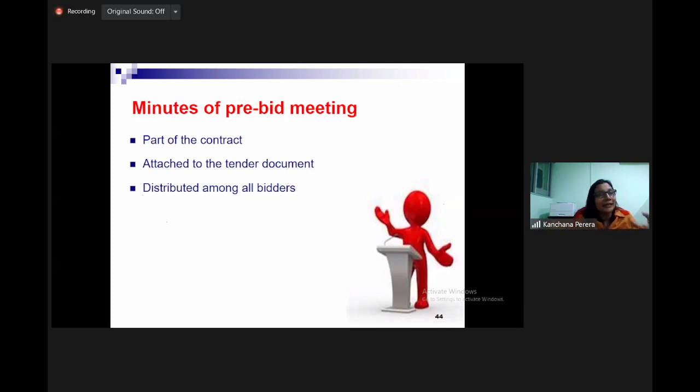If a bidder identifies that the quantity given in the BOQ, the quantity in the slab, in the drawing is different, they can raise questions. As well, if the consultant identifies his mistakes during this period, even he can issue a correction. So the pre-bid meeting is very useful.